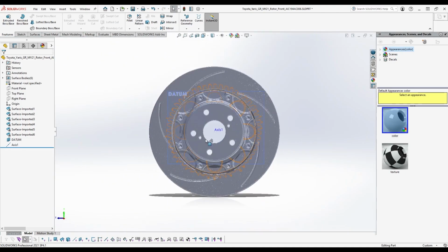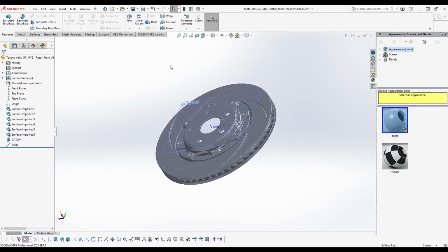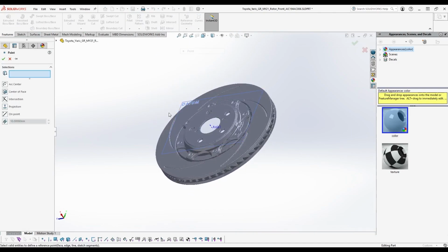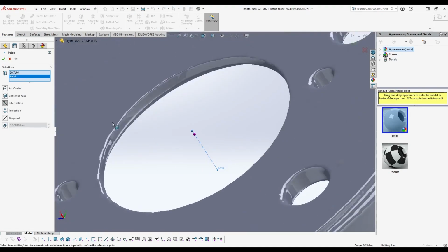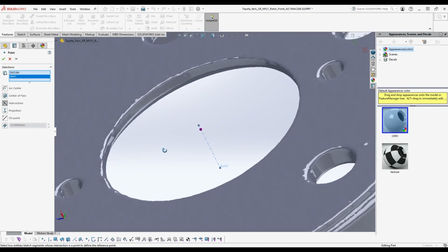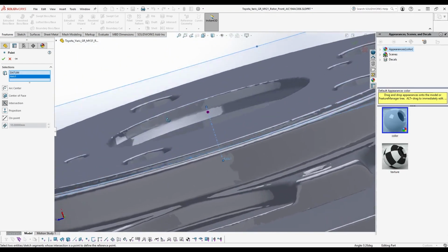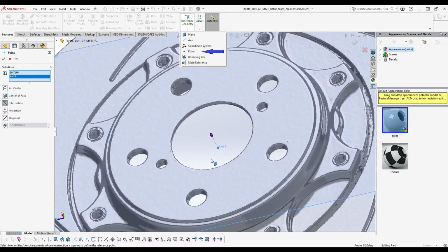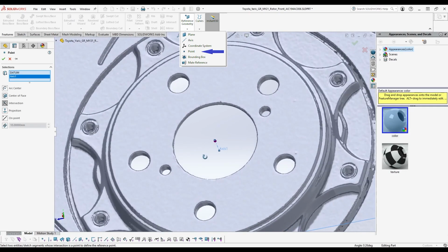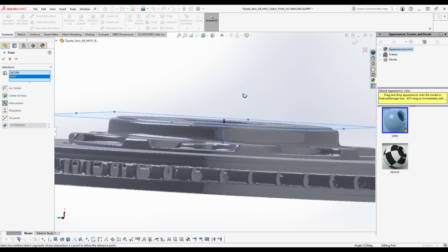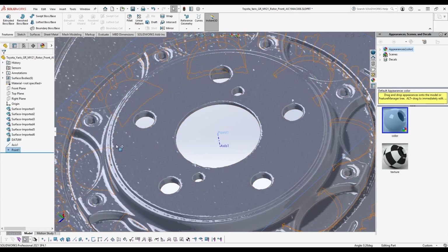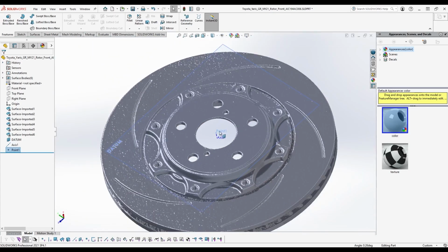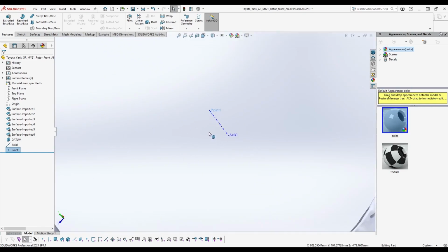So what you're better off doing is creating a point, and the inputs I'm using is the datum plane and the axis, and it's going to say, I'll give you an intersection. So what it's done there is it's given me an intersection point on this plane, but where the axis crosses it. Now, that's going to be very, very close to the center of this hat, and I'll take that, and I'll say thank you very much. And then now I don't really need the axis, but I could remake the axis through that point.